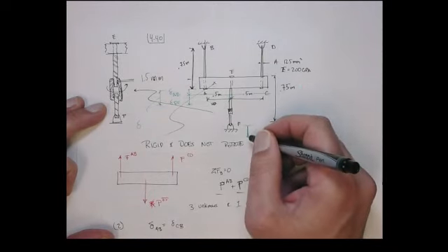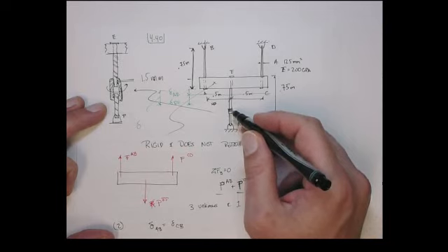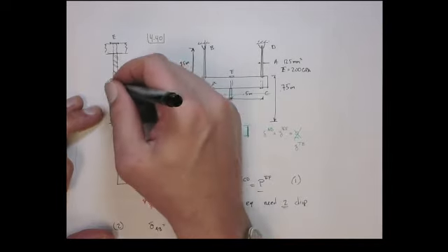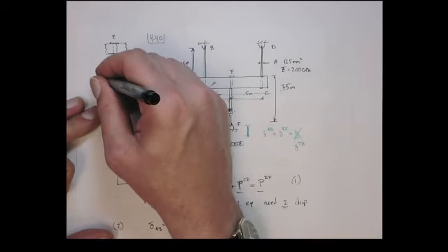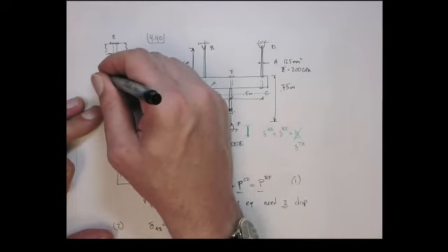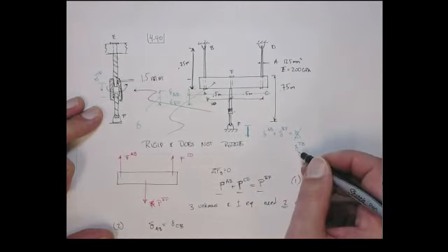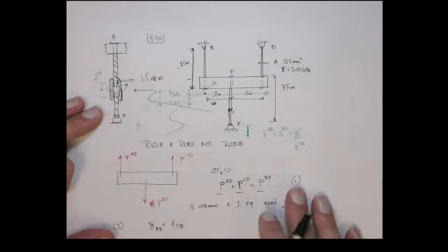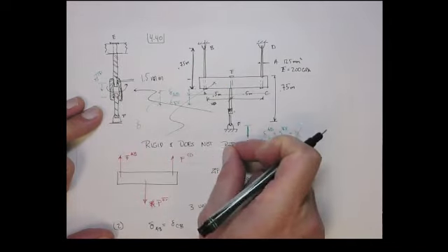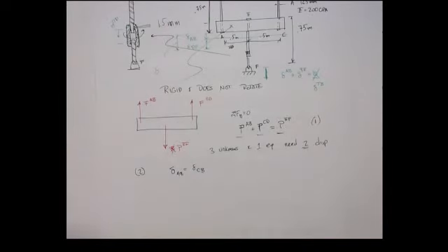Now in this problem you're not actually doing that, but what happens is this amount that the whole system has to elongate is the amount that's picked up in the turnbuckle, right? That's how close these two have to come together. That's the delta in the turnbuckle, okay? So actually what happens is this doesn't go to 0, but this has to equal how much the threads come together in the turnbuckle, all right? So it's the turnbuckle that's, in a sense, pulling this down. So that's the second compatibility equation. I hope I explained that well.